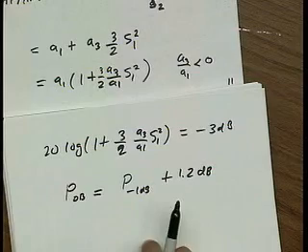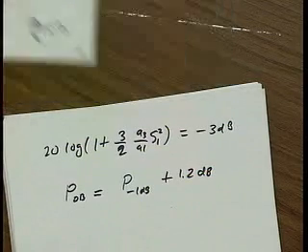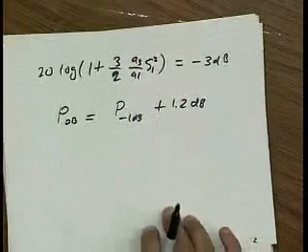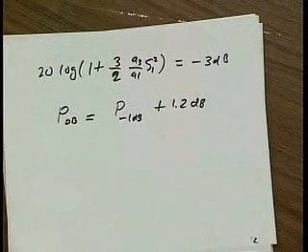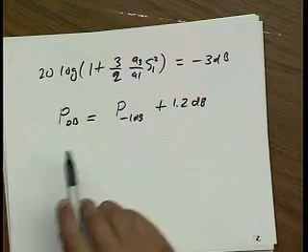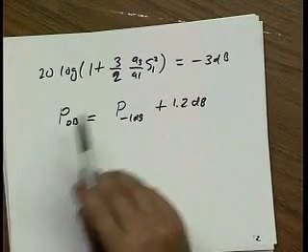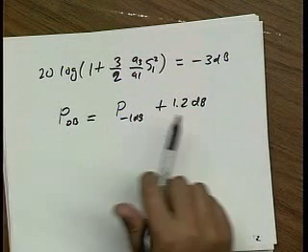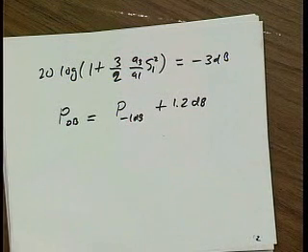Now remember at the beginning of class I said you don't want to operate your system where it gets very nonlinear. Well, this is one important reason why, because if you operate in this region, any kind of interference will completely jam your system and reduce your gain. You're much more susceptible to it here. Okay?